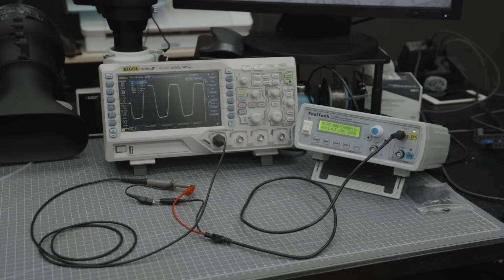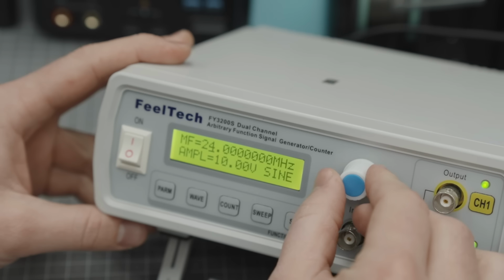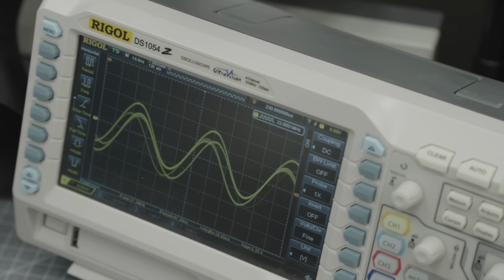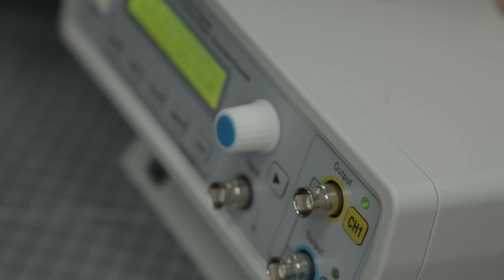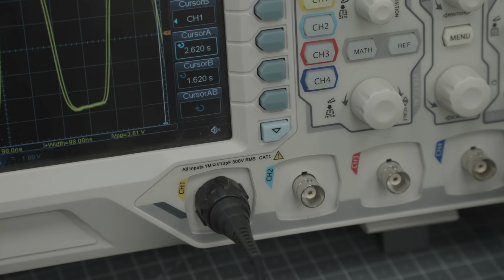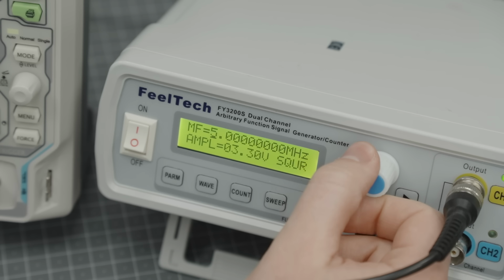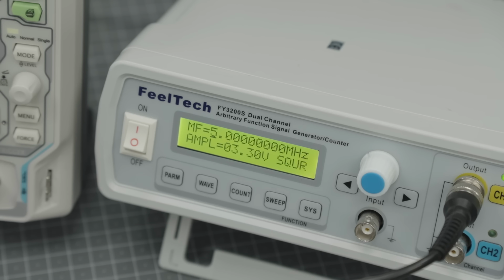Anyways, let's jump in. I've set up my signal generator for a 5 MHz square wave. Technically it can go up to 24 MHz, but things look like a sine wave then instead. I mean, the generator is designed for a 50 ohm load and my logic analyzer and scope are sort of in the mega ohm region. I don't have any proper 50 ohm termination on hand and we're kinda leaving my comfort zone here anyways. Now let's look at a typical workflow.